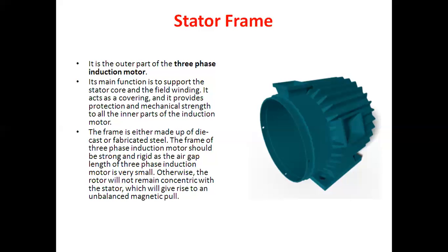And the frame of a three-phase induction motor should be strong and rigid, as the air gap length of the three-phase induction motor is very small. Otherwise, the rotor will not remain concentric with the stator, which will give rise to an unbalanced magnetic pull.